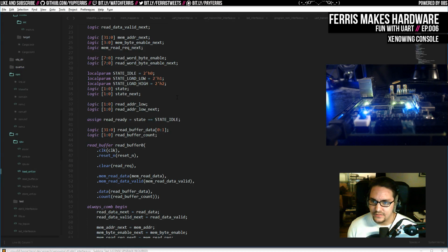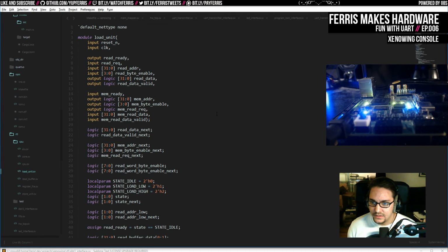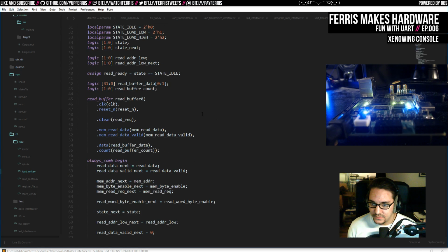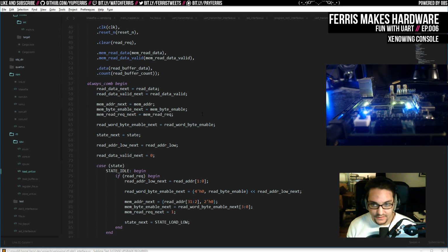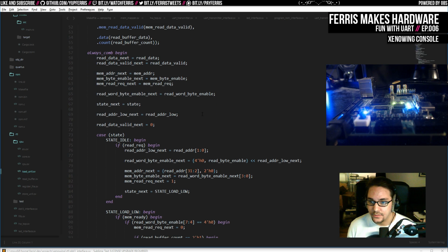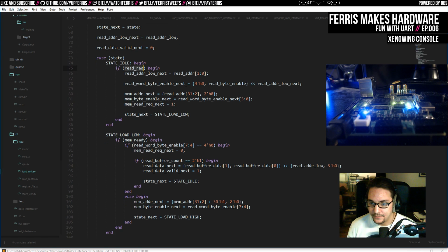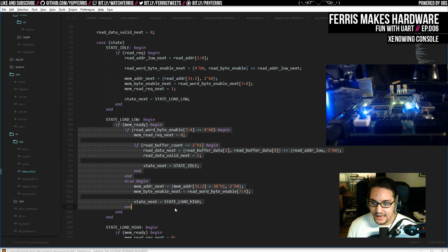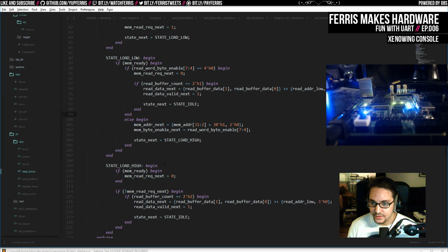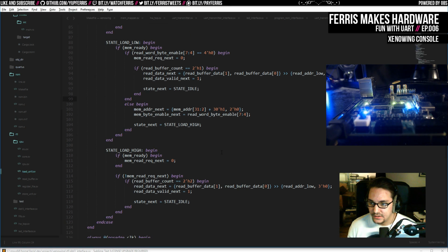The whole idea here really is just that these have their own interface to the core and then to the memory themselves, and they handle all the misaligned stuff. So this is the load unit, and when a read request goes to this, then this will issue it to the memory rather than the core issuing to the memory, and it knows that it may only have to read one of these or do 2 loads here, and that's it. So that ends up being a lot simpler.